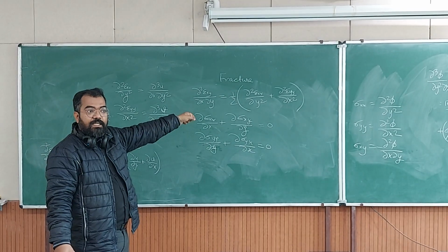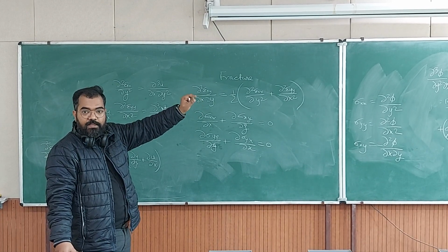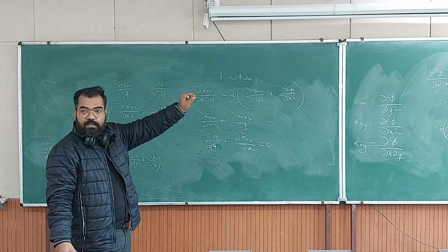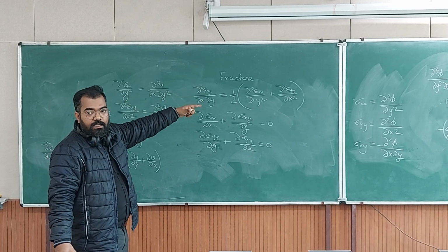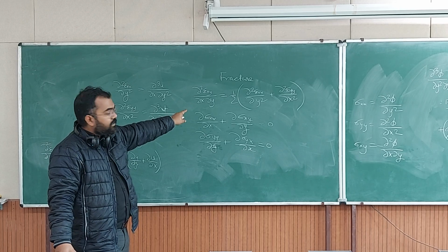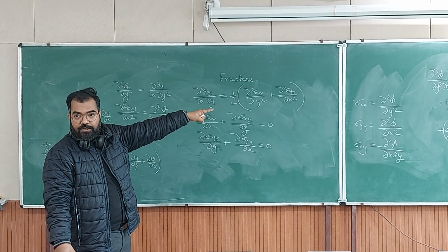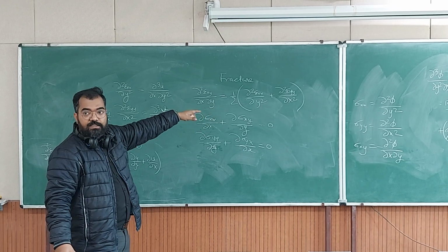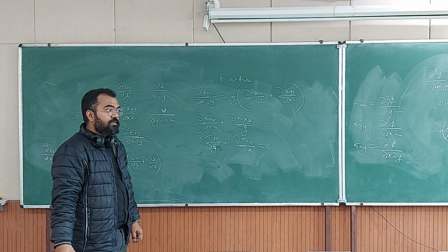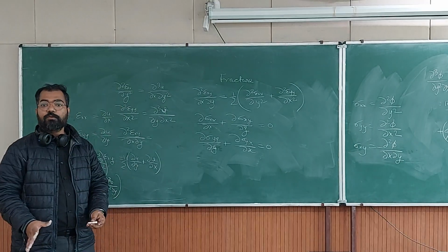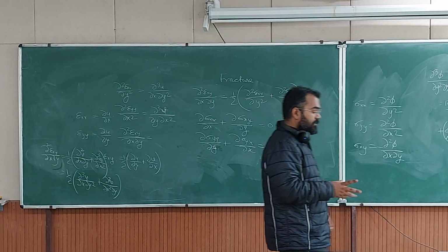So epsilon ij is equal to (1 plus mu) by E sigma ij minus mu by E (sigma xx plus sigma yy plus sigma zz). You use that relationship, find the value of epsilon, and then plug them here with the definition of the function in terms of phi, and you will see that they also get satisfied. Okay? So then the end will be to define phi. What should phi be? That we'll do in the next class.